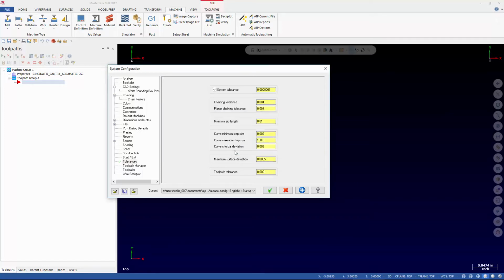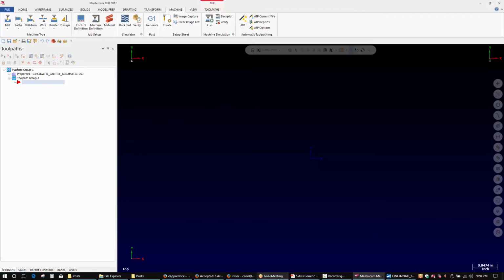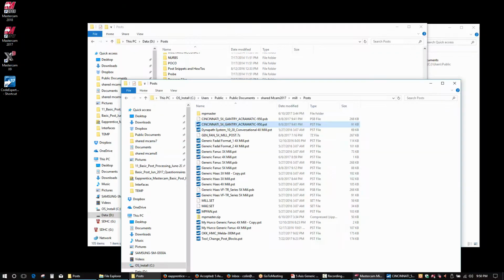And what they're also saying is to use longer tool vectors, especially with a gantry. This is where it really kind of will get you. Even on a trunnion, when you are going around a corner that's got a lot of rotation and your tool axis vectors are really close together, you can get rounding issues. And that's basically what they're talking about there.